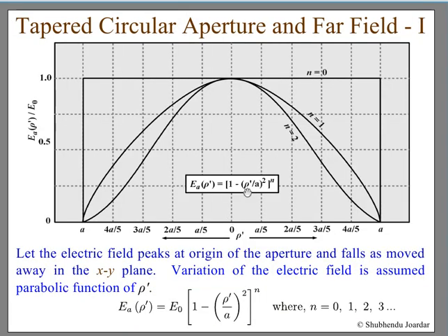So you should remember this for circular aperture, and for rectangular aperture, what the differences may be when you increase the area, what happens. These are the things you have to think about if you want to change the directivity, and this should work as intuition at the back of your mind. Finally, the mathematical relations will tell you exactly how to do it.